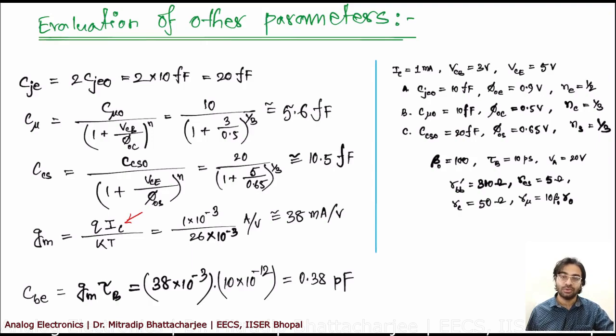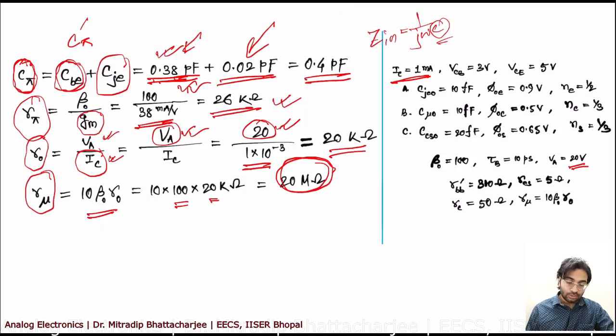At least you should know these are in femtofarad range. So this will give you an idea, typical values. These are okay. In special cases they may vary. In special cases you also may need to do something where the CJE is probably not femto. You want this to be pico. That is a different case. But at least the typical values you will get from here. So these 2 slides are important.